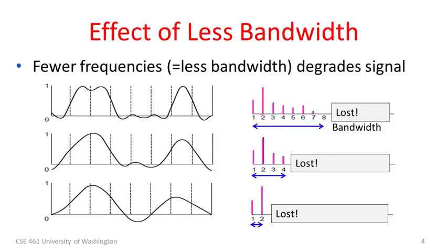As you lower the bandwidth, there's a pronounced effect. As you lower the bandwidth, this means that fewer and fewer frequencies can get through, only the lower frequencies which oscillate less quickly. So you can see here in this box lost, I've taken the signal from before and I've scrubbed out all of the frequency components over 8 times the fundamental. This means that the components that I have left can only make transitions less rapidly.